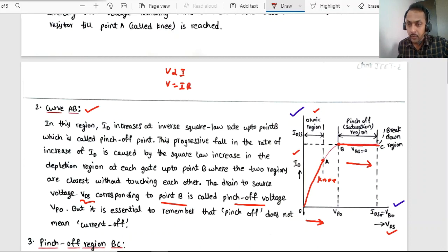Another interesting feature you can also observe: the drain current remains constant only up to a certain point of VDS voltage. Once the drain source voltage has crossed a certain point, from there onwards the current will be no more constant. All of a sudden there will be a breakdown, a high rise in the drain current. Very interesting features we can observe in these characteristics. To some extent it behaved like a linear resistor. After that point it is not linear.